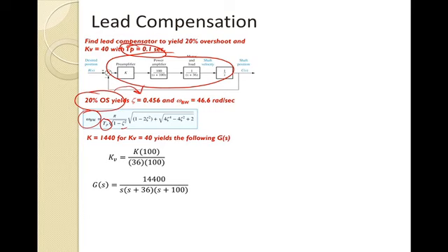And then once I have that damping and the peak time given there, I can literally walk through this. This is not an easy calculation. There are a lot of possibilities for errors here. So make sure you can physically substitute all this in and get the closed loop bandwidth of 46.6 that I'm showing here. It looks easy. It's on the slide, but please go through the steps.